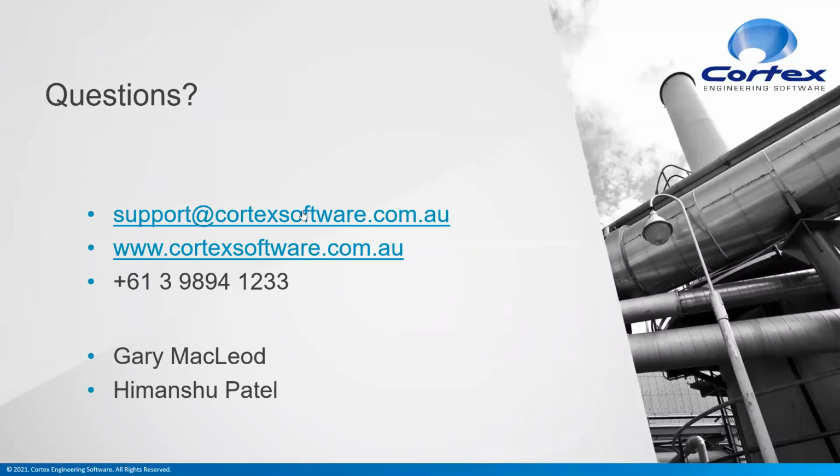With the fluid moving through the pipe, the friction on the pipe walls, for example, will be taken into account in that calculation. It's a very detailed calculation. To do the calculations, Xstream must include thermodynamic functions, state equations and those sorts of things. And friction is one of them.